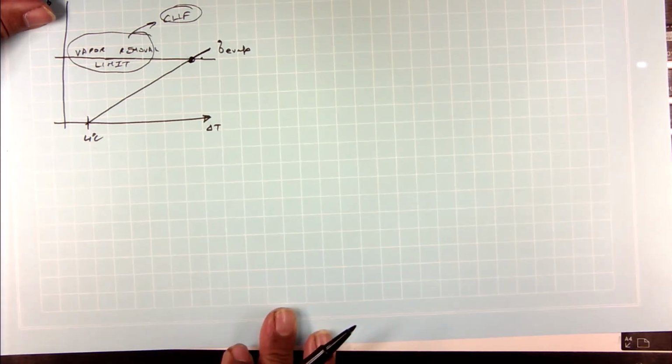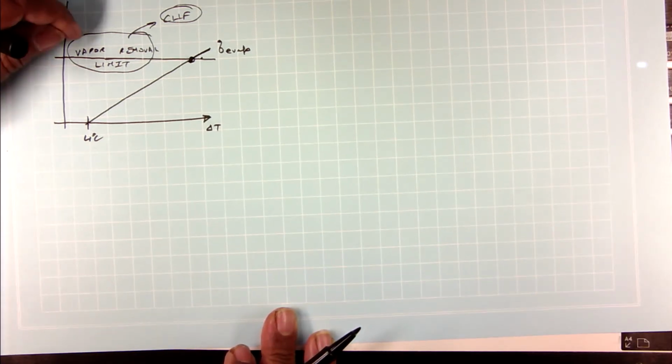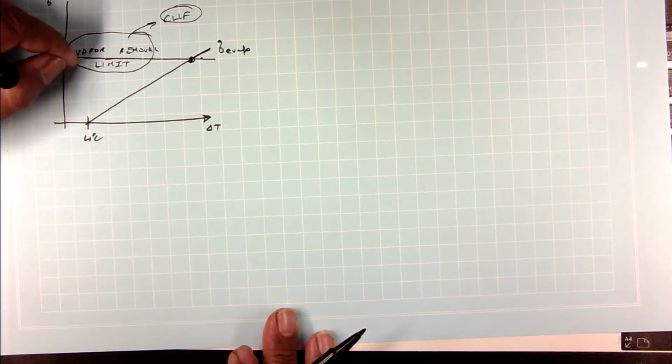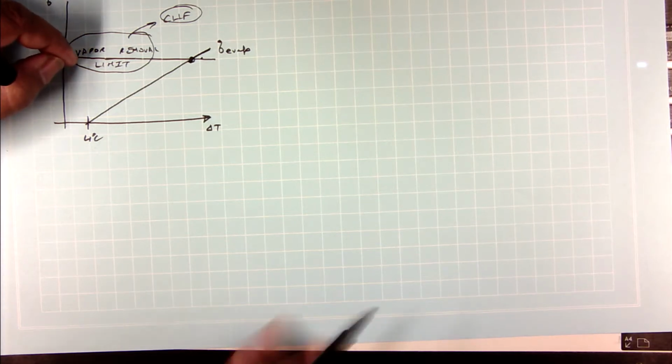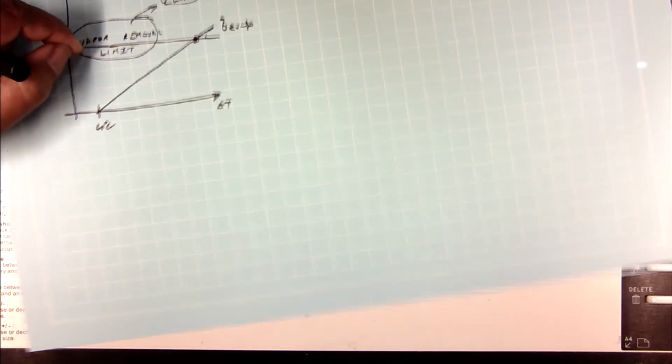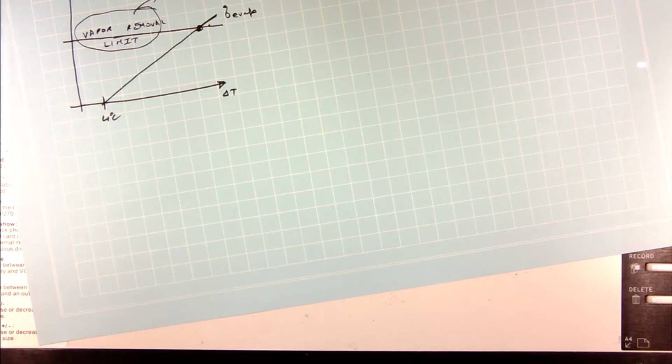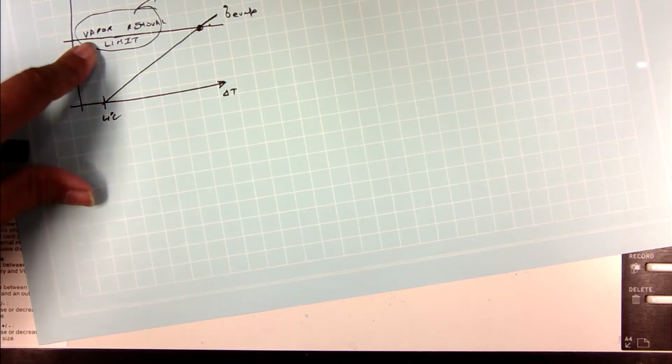Yeah, agreed? But if I start having flow boiling, then this limit is gone, because the moment a vapor bubble is produced, I can pump at really high speed and take the vapor bubble out of my system, isn't it? So here the vapor removal limit is your terminal velocity of the bubble, right? But the moment I have flow boiling happening where the bulk of the liquid flows, then I have done away with this limit, because now my flow rate determines how fast I can take the vapor bubble out of the system.